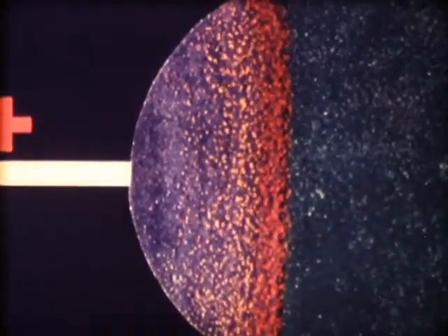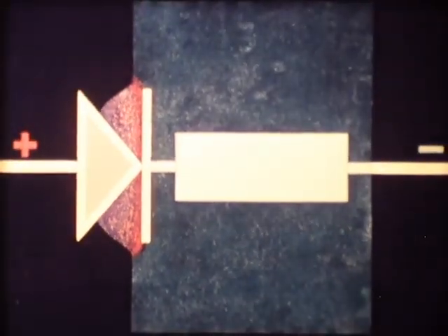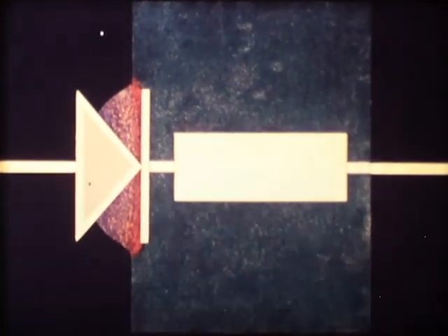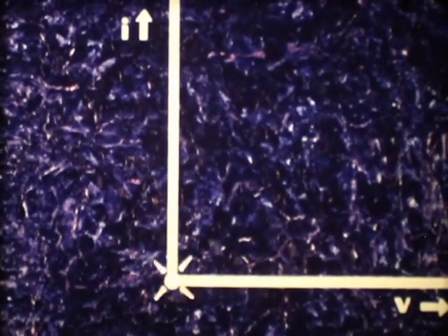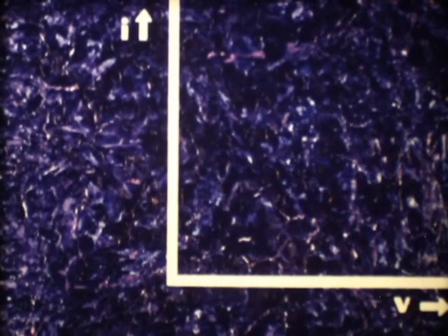The equivalent circuit of a diode having a forward voltage applied to it consists of a junction in series with the resistance of the N-type material. In order to find the current voltage characteristic of the diode, we should first study the current voltage characteristic of the junction. Without this forward voltage being applied, the minority concentrations will return to the equilibrium level, which is here 10 to the 10th per cubic centimeter. In the junction characteristic, the situation is represented by this point, because both voltage and current are zero.